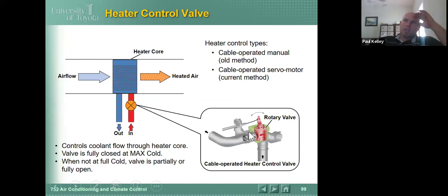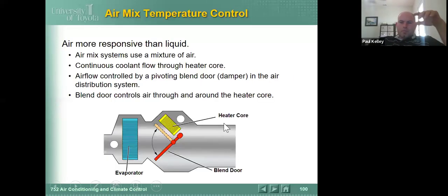So that would be one type. This is not real common. Honda's used it for a long time, but mostly they don't now. So kind of makes sense, right? This is the one we just talked about. This blend door or temperature door directs air this way, directs air this way. You want it hot, you want it cold.